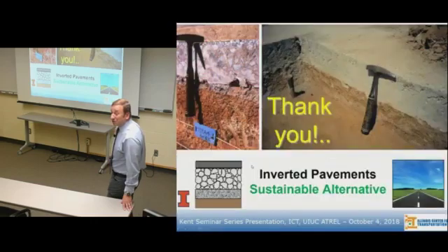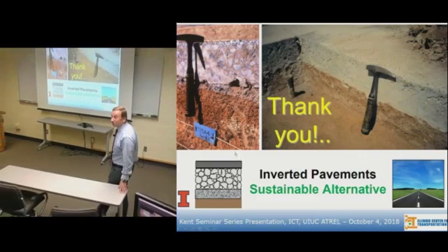Altogether, I think inverted pavement is a good alternative. It's a sustainable alternative. It utilizes engineered application of an aggregate base over a cement stabilized layer. And when everything is constructed right, you've seen examples, this is a truly winner pavement test section construction technique and a design alternative.